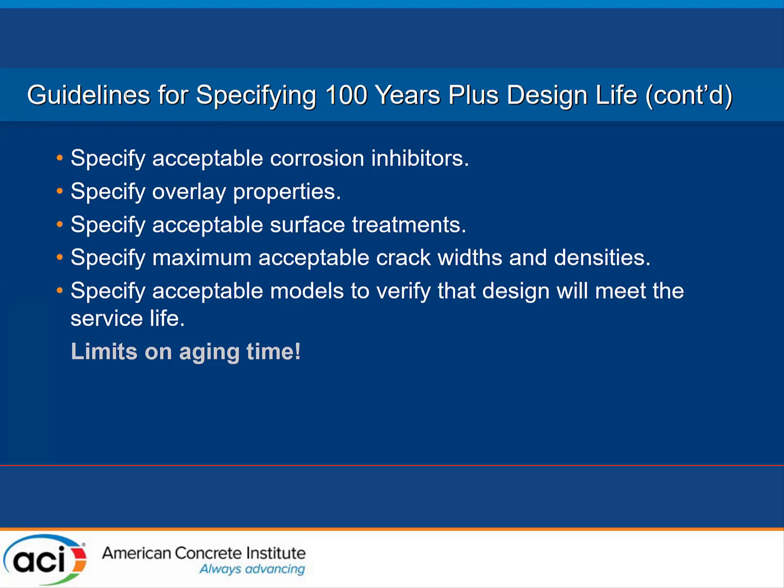You should say something about maximum acceptable crack widths and densities, which hasn't been mentioned up until now. And specify acceptable models to verify that the design will meet the service life. And you've got to watch your model, what limits it puts on hydration time, because concrete will not continually hydrate forever.